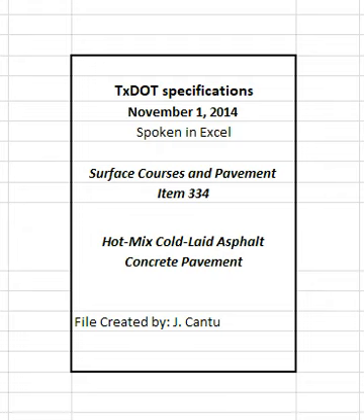4.5 Compaction. Furnish the type, size, and number of rollers required for compaction as approved. Furnish at least one medium pneumatic tire roller, minimum 12-ton weight. Use the control strip method given in TxDOT 207F, Part 4, to establish rolling patterns that achieve maximum compaction. Follow the selected rolling pattern unless changes that affect compaction occur in the mixture or placement conditions. Establish a new rolling pattern when such changes occur. Compact the pavement to the cross-section of the finished paving mixture meeting the requirements of the plans and specifications.